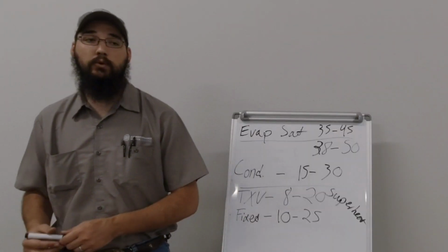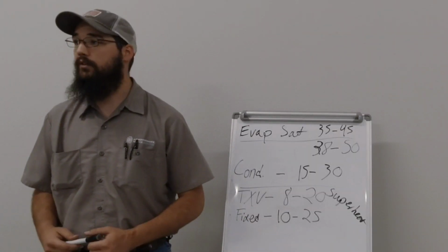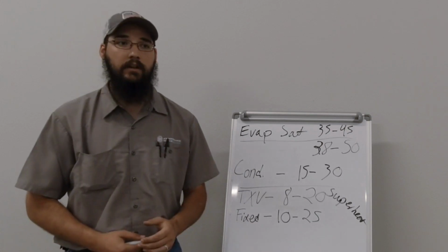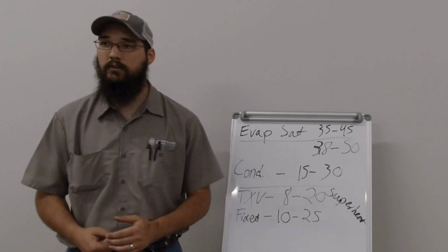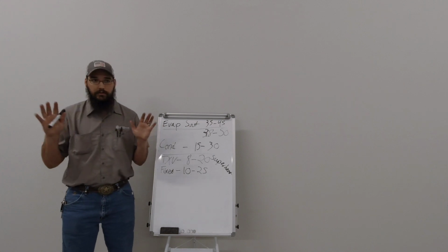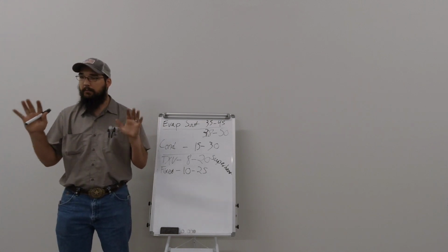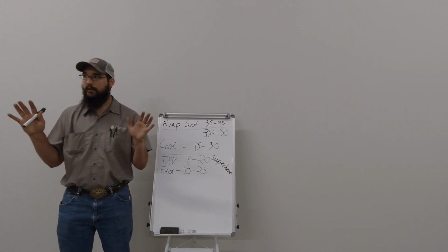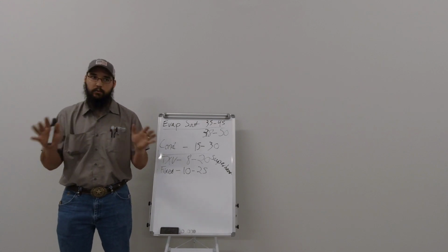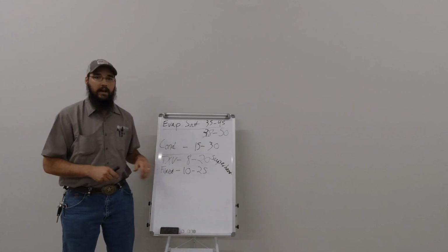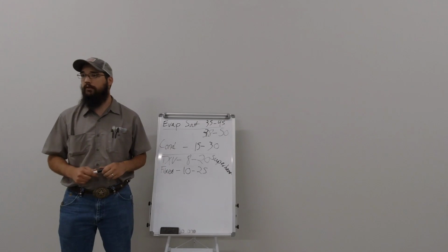On the flip side of that, if it's too high, now you can't cool the compressor down enough and it begins to overheat everything. And it's only going to take that for so long. We have the ability, it also depends on the design and setup and install, right? We can only affect that so far as to that point. But we have the ability to decide just how much life that system's going to have versus not.